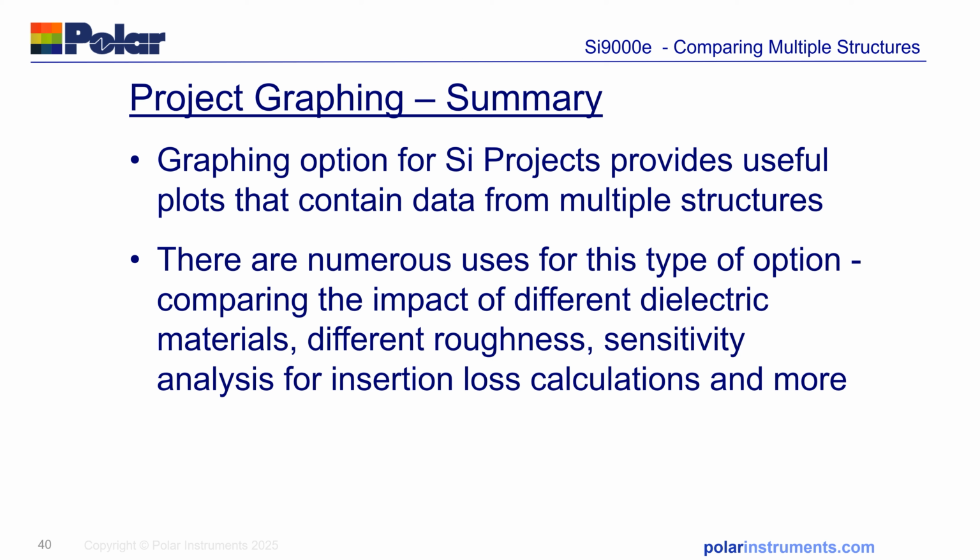So in summary, the graphing option for SI projects provides useful plots to contain data from multiple structures. There are numerous uses for this type of option, comparing the impact of different dielectric materials, different roughness, sensitivity analysis for insertion loss calculations, and more.